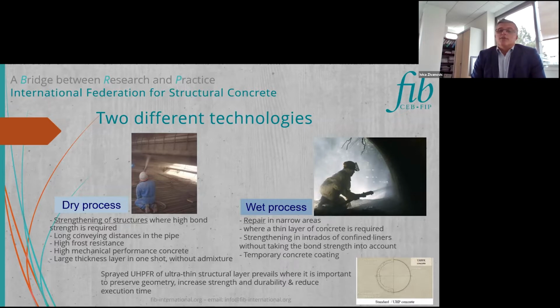Of course, now with the improvement of concrete itself, it is possible to spray ultra high performance fiber reinforced concrete or ultra thin structural layers, which prevail where it is important to preserve the geometry, so as not to significantly impact the internal clearance, for example, and to increase the strength and durability.